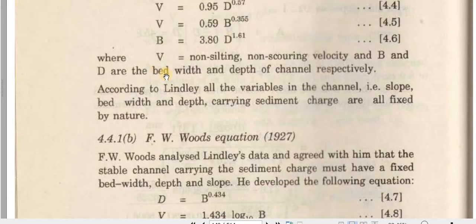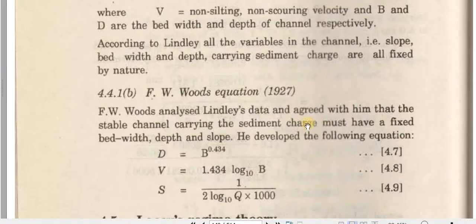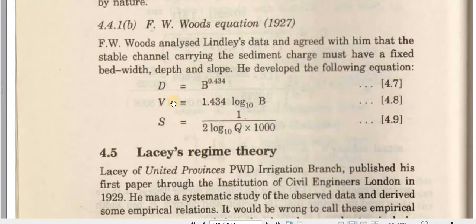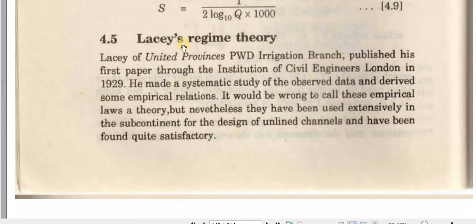He analyzed the data of E.S. Lindley, and he agreed with him that the stable channel carrying the sediment charge must have a fixed bed width, depth and slope. So he introduced depth and bed width relation, velocity and bed width relation, and slope versus discharge relation. And the third is Lacey regime theory.